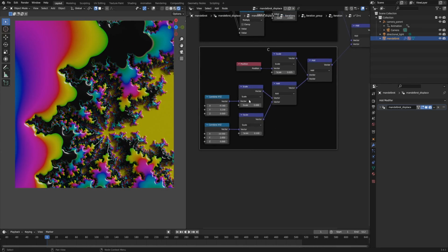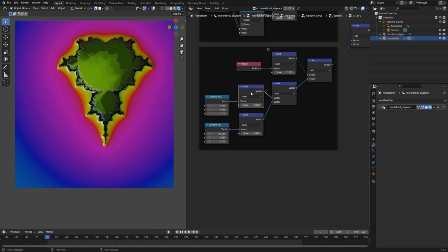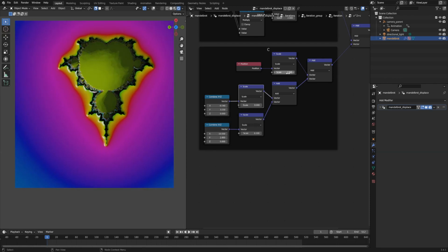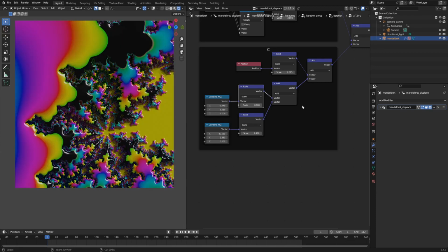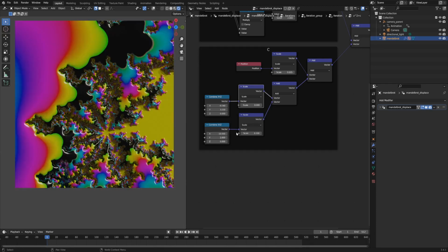And so I've got one translation scaled to a very low value. It just says 000 here, but it's actually 0.0001. And then a slightly higher value, and that's so that when I'm scaled at different distances, I can move quicker using this to find a spot. But when I'm zoomed in a lot closer, if I move these values, I'm just going to move really quickly. So I want a bit more fine-grained control.